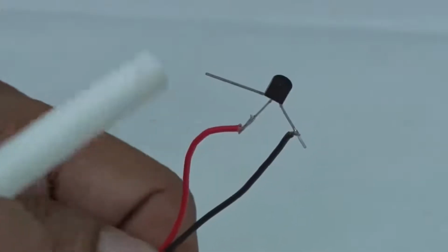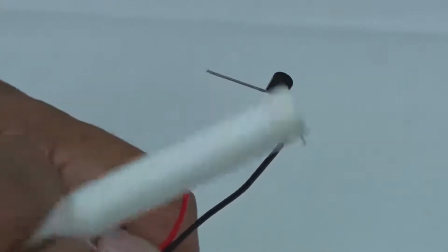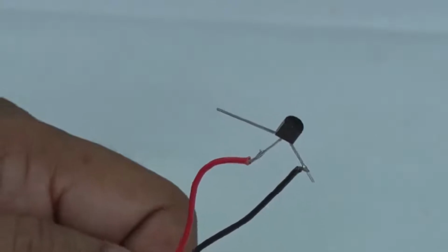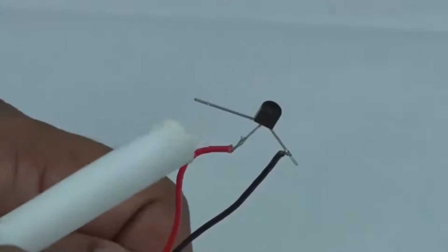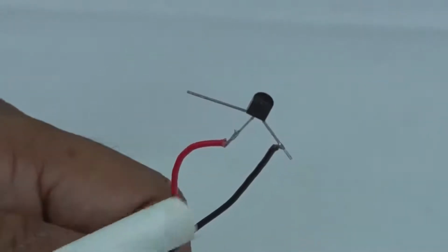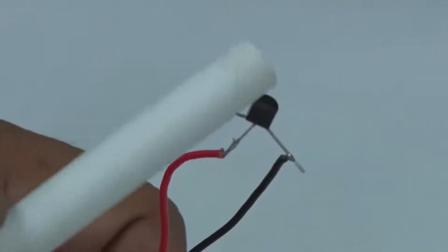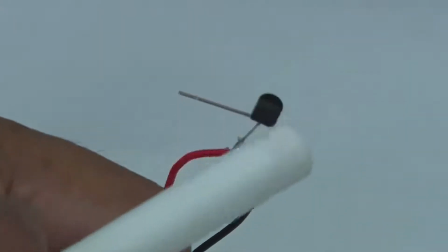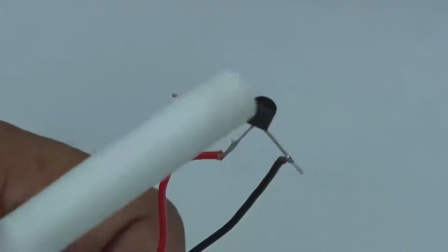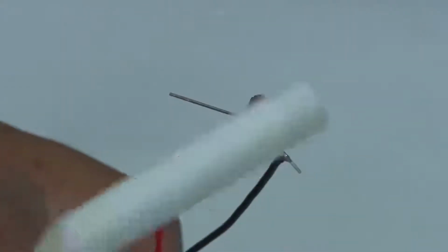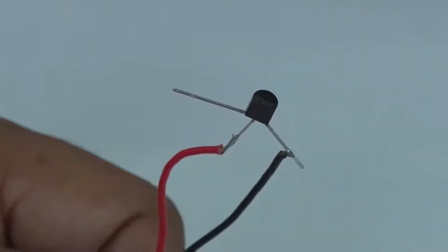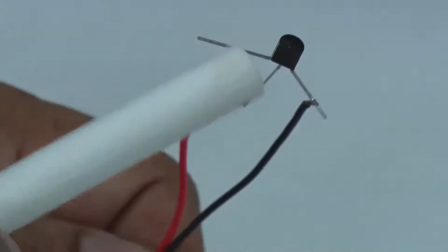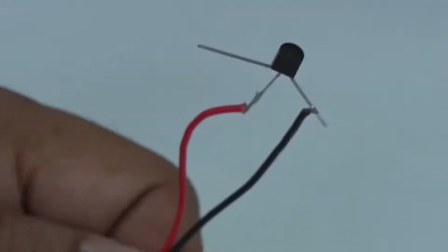This is a low power transistor, used for small currents. Then you have other kinds of transistors where the casing is metallic, a full cylindrical type, and from the bottom there are 3 leads coming out. On the circular cross section at the top there is a notch, from which people identify the first lead, second lead and third lead, and then the data sheet will say which is emitter, which is collector, and which is base. So this is it. I will just show a particular experiment with this transistor.